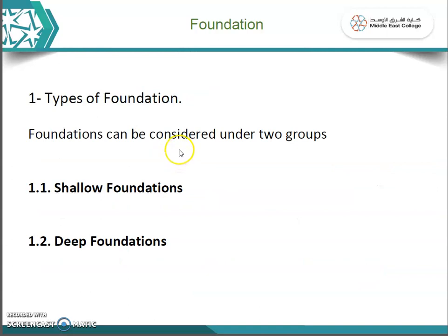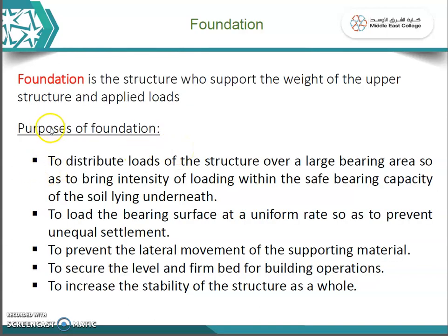We are going to discuss the purpose of foundation. The purpose of the foundation is to distribute loads of the structure over a large bearing area so as to bring the intensity of load within the safe bearing capacity of the soil lying underneath, below the ground surface. So this is the basic purpose of the foundation: to distribute the loads carried by a structure and transfer them to the substructure, through the ground.